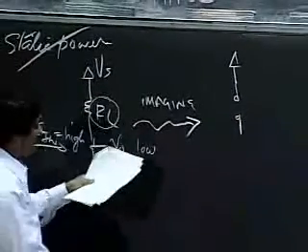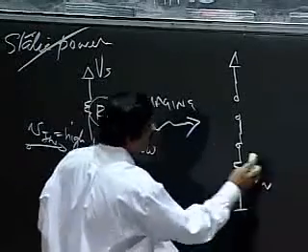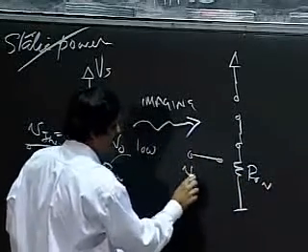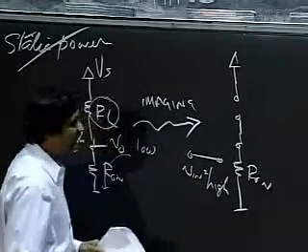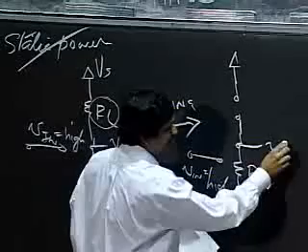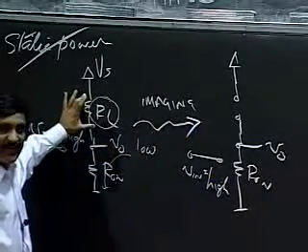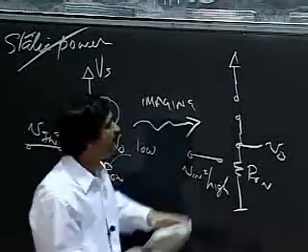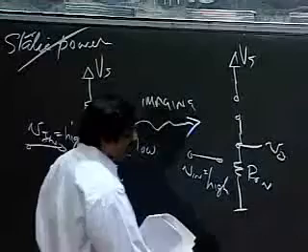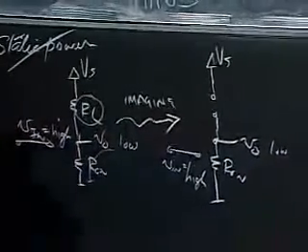Imagine I could open circuit this guy, R on. So when Vin was high, instead of having an RL here, what if somehow I could make this RL become infinity? In this case, output VO would be low.